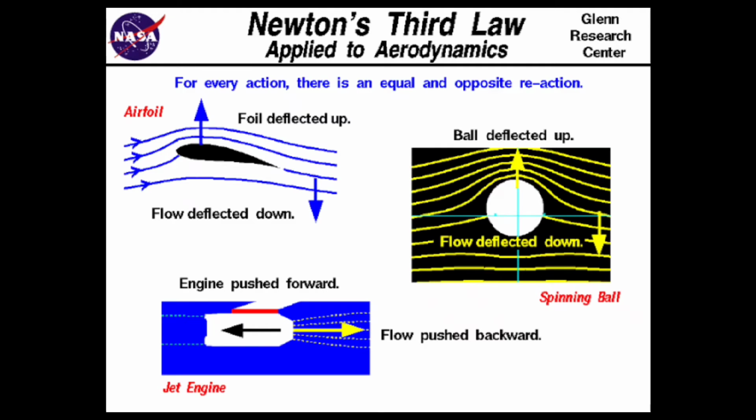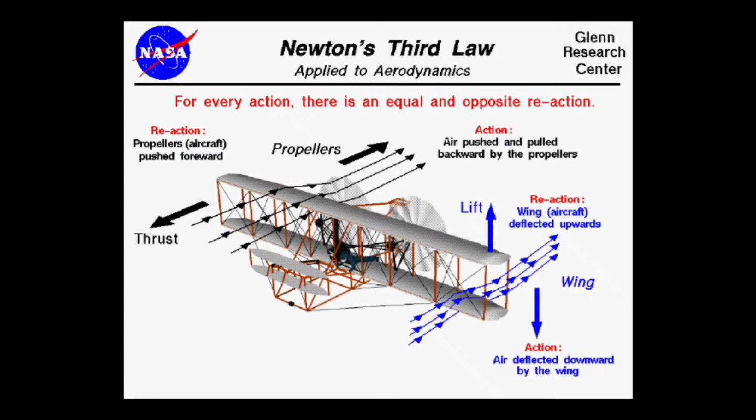One of the argued but commonly discounted theories of lift generation is related to Newton's third law of action and reaction, whereby the air being deflected downwards off the lower surface of the wing creates an opposite reaction, effectively pushing the wing upwards. This may well be the case, but it's the pressure difference between both surfaces that is the commonly agreed factor of lift generation.